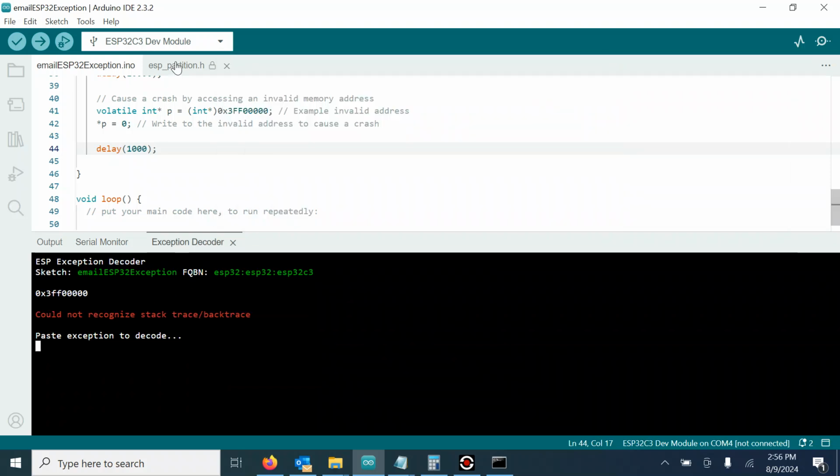And somebody made a patch where you can add this to version 2 Arduino, but it's not compatible with the newer chips. I'm using the ESP32-C3, but it's the same as the S3. And the difference is the architecture. The newer chips are the RISC-V architecture, and the older chips are the Tensilica architecture. So this will not work. Close that.